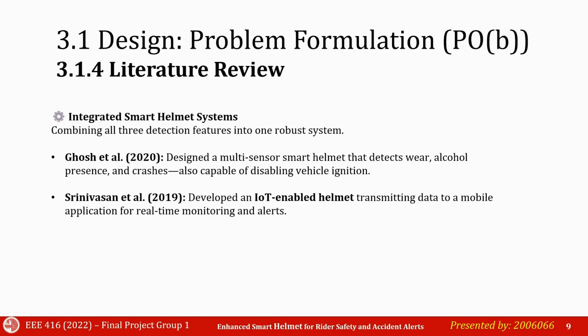As the mobile app is not that efficient in an emergency context, we did it with a GPS module from which we take the location and send it via a GSM module by a message or a call, so that the emergency contact can be notified at that exact moment.